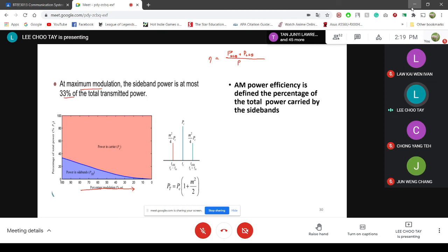Then after that, we treat the single sideband that we have filtered out as a new baseband signal, and only now we modulate with the high frequency carrier. Okay, so that is Weaver's method. And why do we do it in two stages instead of one stage? Again, in one stage we know we have a problem designing the filter. The benefit comes from filtering being much easier at low frequency as compared to high frequency.